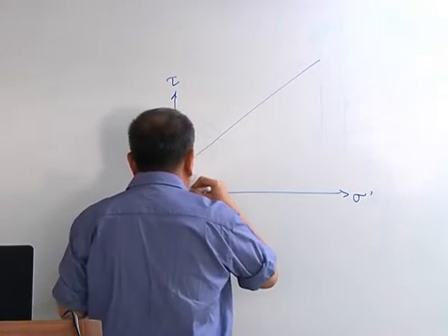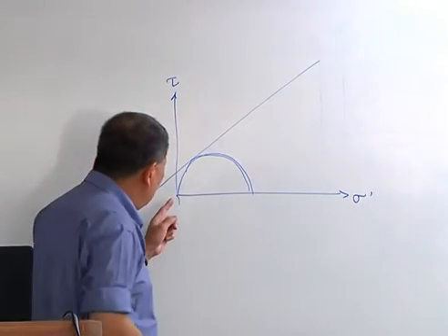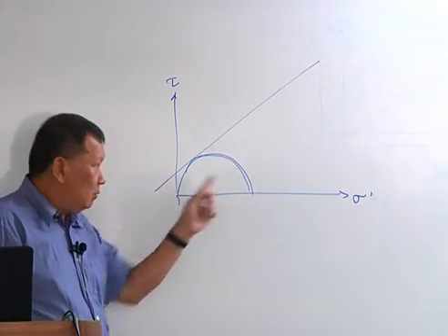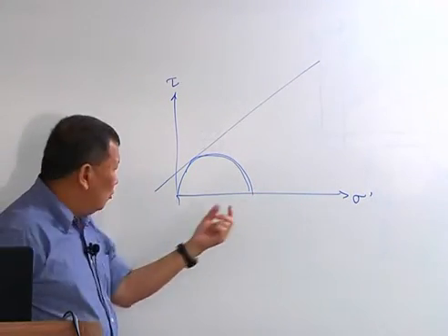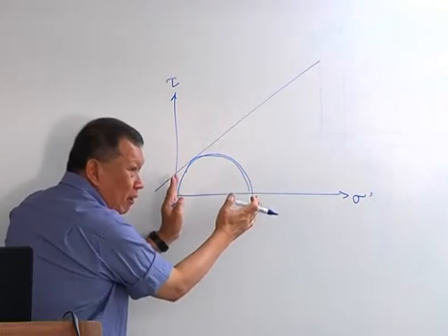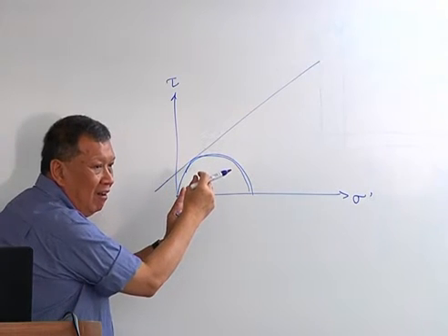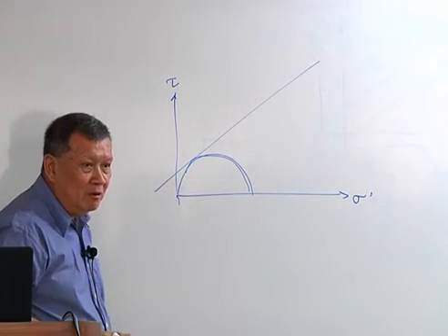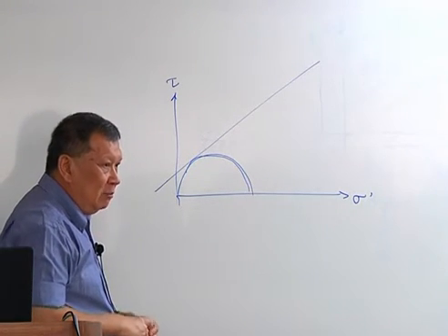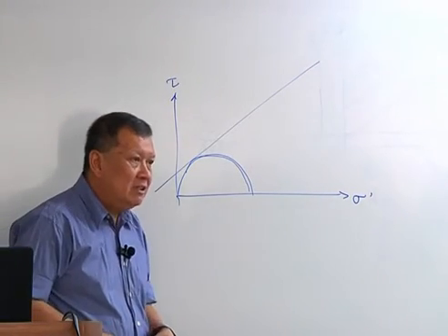Now, the limiting Mohr circle will be this. Basically what it means is the end point of this Mohr circle cannot go negative, because sigma r' cannot go negative. So your Mohr circle cannot move this way. It can only reach this point. So there is some region over here you cannot explore with the Mohr circle. You got it? So it doesn't mean the triaxial test can actually go all the way. It cannot. There is a certain region it cannot go.